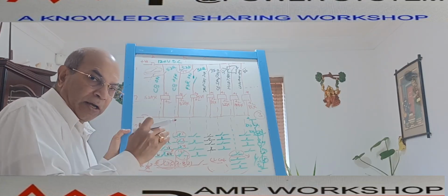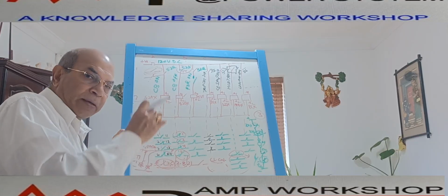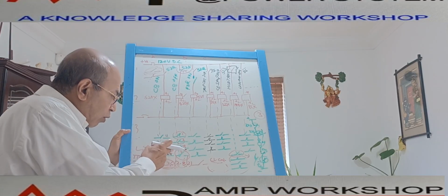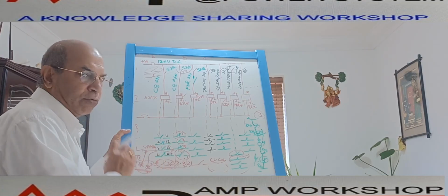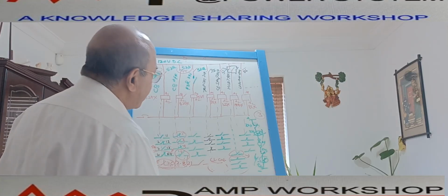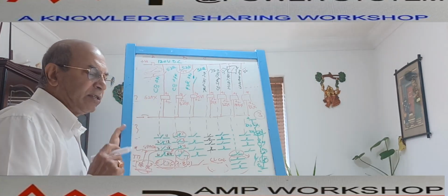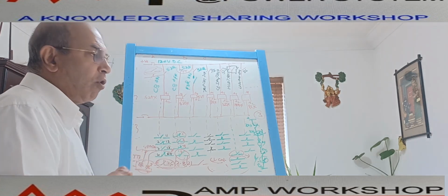From the relay body pin, because this is an auxiliary relay, this contact is wired up to the field terminal block, terminal number 1 and 3. That is also what we show. In addition to this, there is another special feature, the circuit breaker on or off.